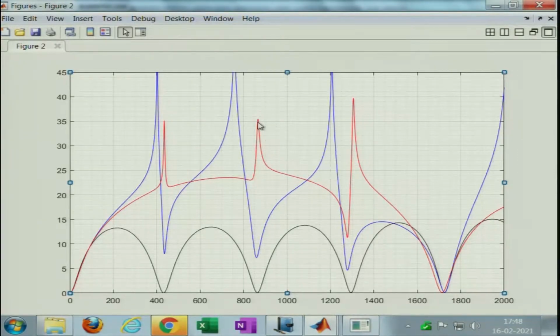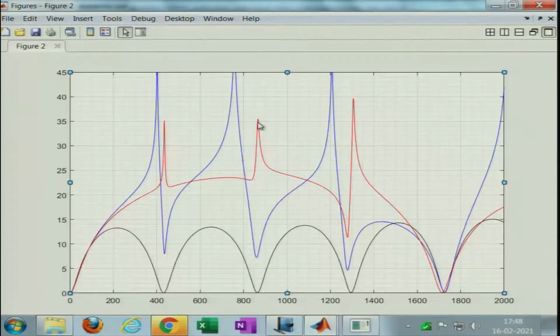almost nullified the trough. So basically what has happened is that because of the perforate impedance, the exact tuning, if you choose LA equal to L by 2, does not really tune it based on the plane wave theory. It kind of mismatches the trough. So by choosing an appropriate length, we can actually tune the performance, and this happens by trial and error. But then we have to wait and watch.